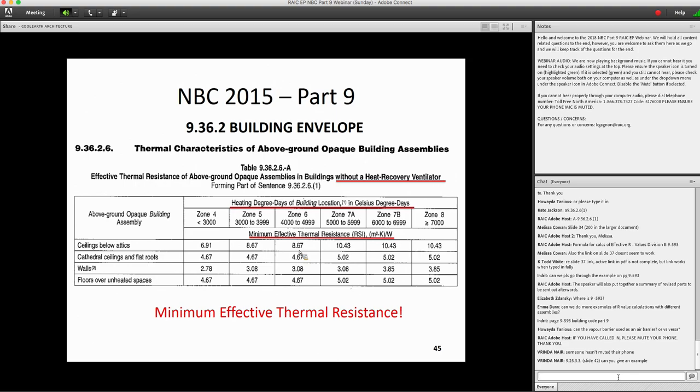So depending on the area that you go, let's say that we are in Regina, Saskatchewan. So we have degree days below 18 is 5,600. So if we want to get the minimum thermal resistance of the assemblies for Regina, Saskatchewan, we are at 1,500. So we are in zone 7A. So we will get, can you see this? 7A. So we'll have to use this table. Okay?